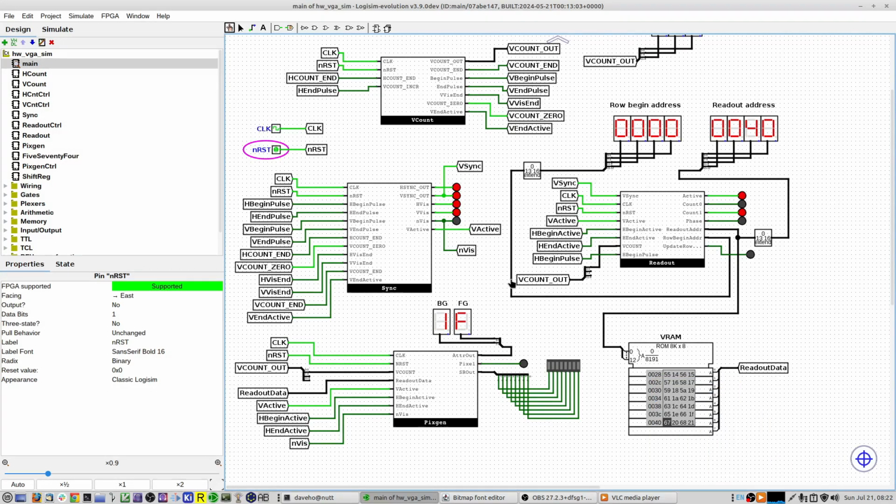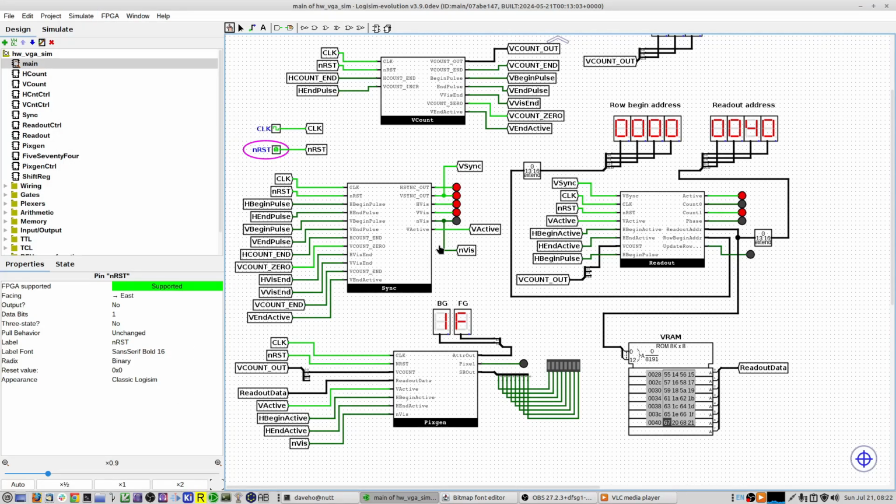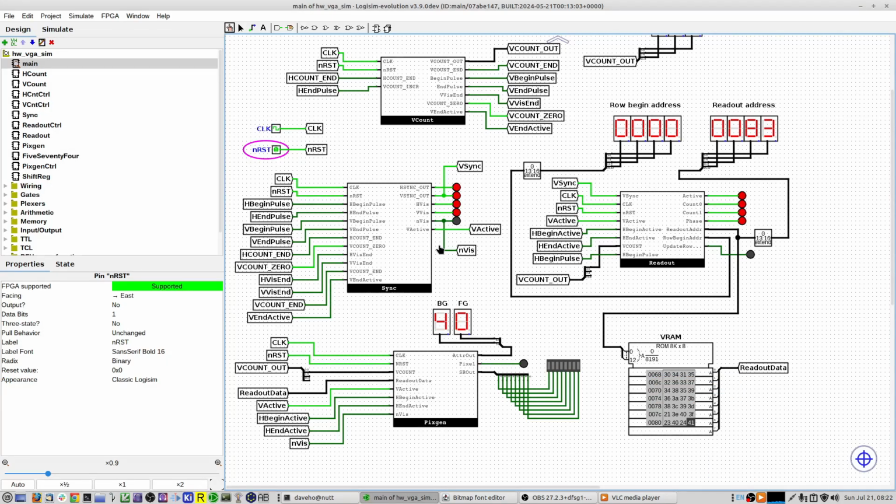All right, so yeah, we're actually quite close here. Let me slow down the simulation quite a bit. All right, we're very close now, so I'm going to manually clock this. There is the caret symbol being fetched from video memory. It's going to take a few cycles until that data is loaded into the shift register. Right, now we're fetching the attribute. There we go. There's that caret pixel.